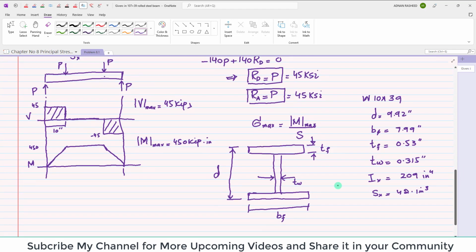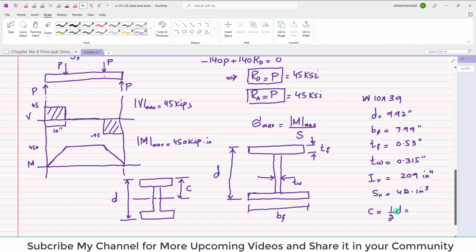Now you can see, if I draw this beam again, this is the total D. Half of D will be the neutral axis, and from the neutral axis to the outermost surface it will be C, and this C is equal to 1 over 2 into D. If you put the value of D, 9.92, and divide it by 2, it gives you 4.96 inch.